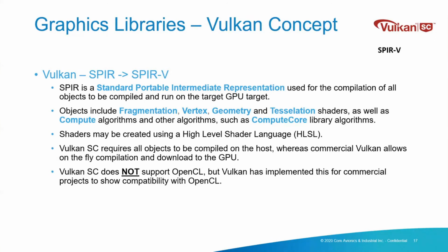Okay, thank you. I have another question, Robert. You mentioned real-time operating system, but you didn't mention bare metal approach on your slide. Is it possible, and what are the use cases? Yeah, it's always possible. We've had a few bare metal projects in the past on typically i.MX6, maybe i.MX8 in the future, just using bare metal with a GCC library that can be compiled with a very simple scheduler. Yeah, it's possible.